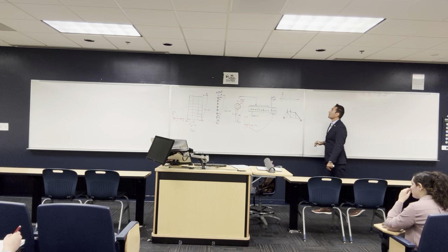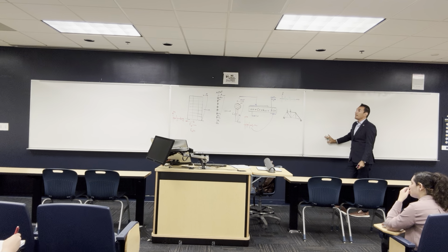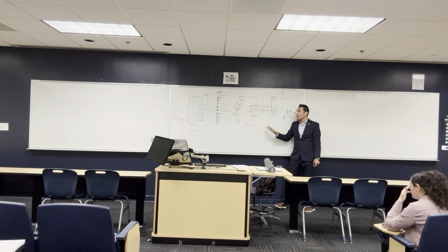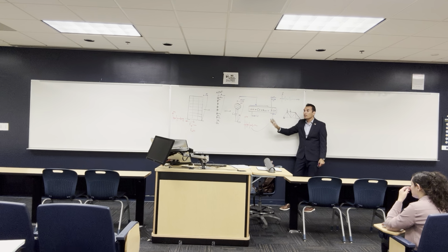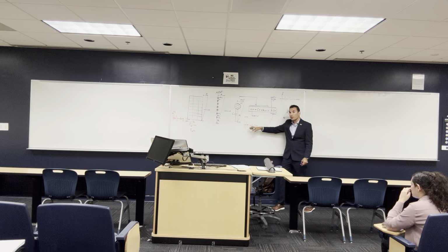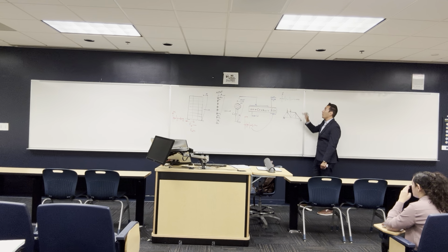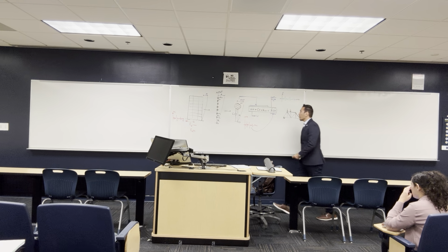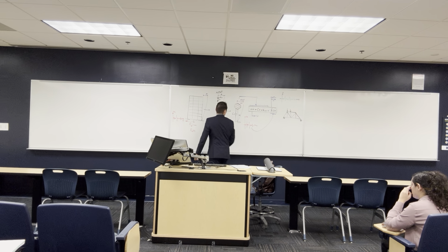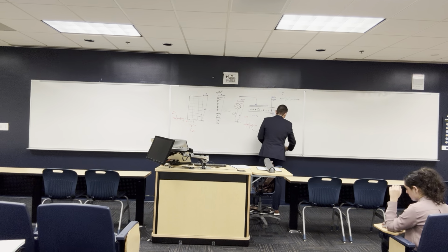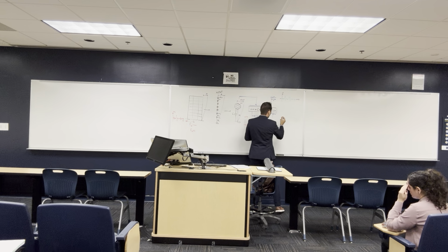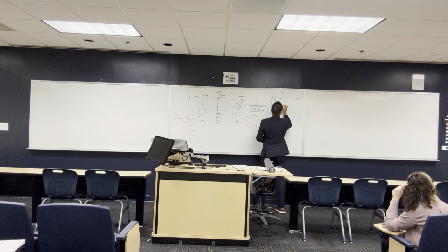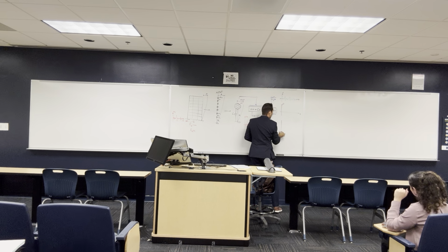Something like this. How does the displacement look? How can we find this? Basically, they divide this curve into a bunch of pieces, and they integrate the equation from time 0 to time t to get all this history of displacement. And the same way, we can do it to get the velocity of the building, and the velocity is u dot.